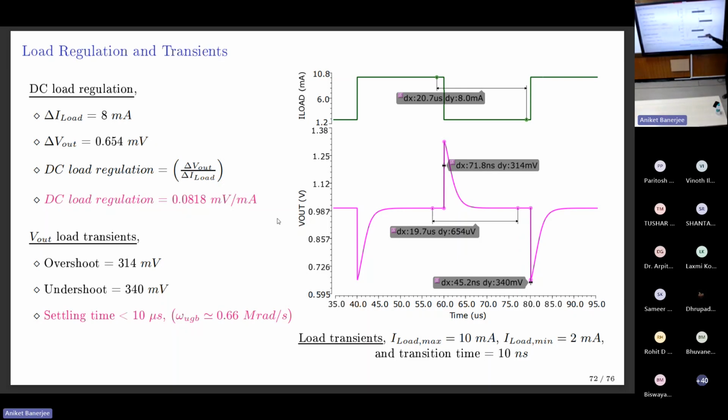So the methodology will change. This methodology is now PSRR matching to gm and ro, then ID/W and fT, and then W/L. Now we want Vn and f squared as a function of gm, ro, and ID/L. There are a few of these where we started working. The methodology will change. This is only a sizing methodology, not the best LDO performance. Given the LDO performance, you know how to come up with W/Ls of all MOSFETs, and you get the same numbers at the first iteration. So this is only a methodology. The mapping portion has to be done by us, from noise to gm and ro.